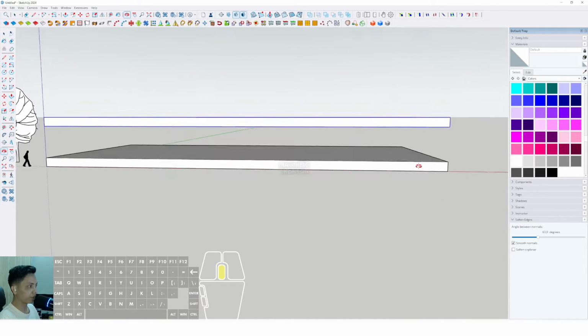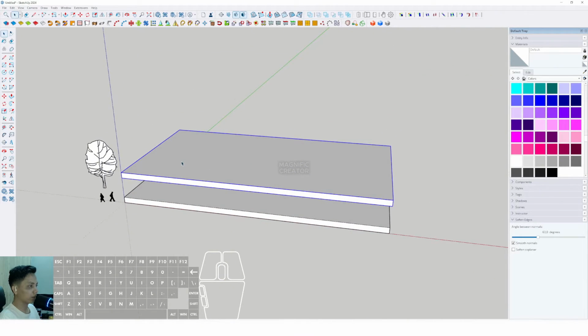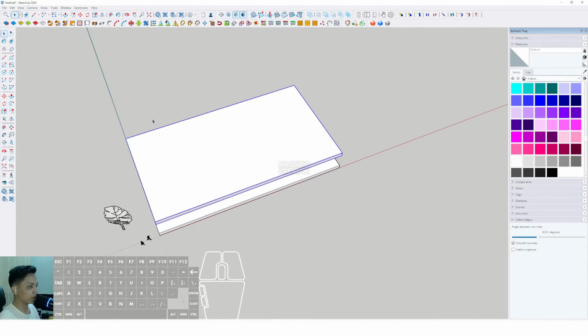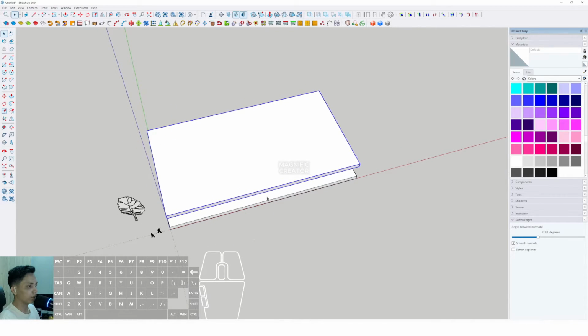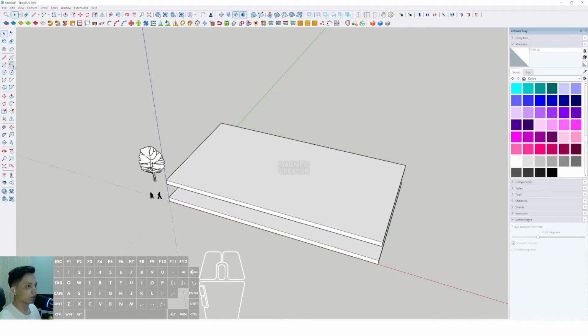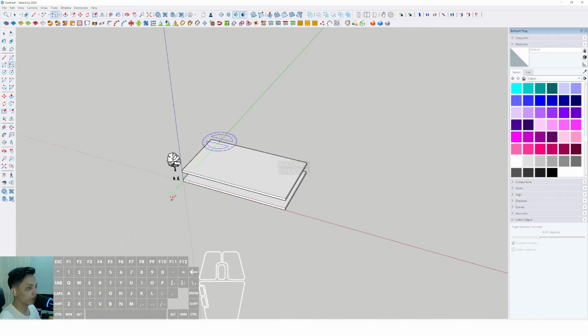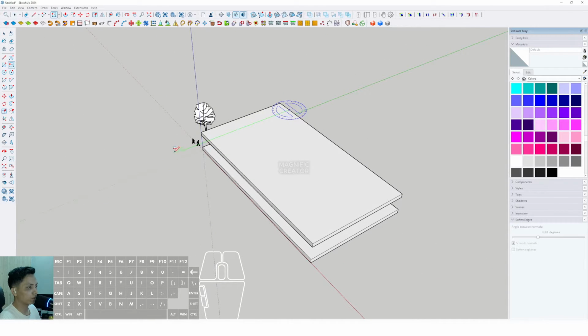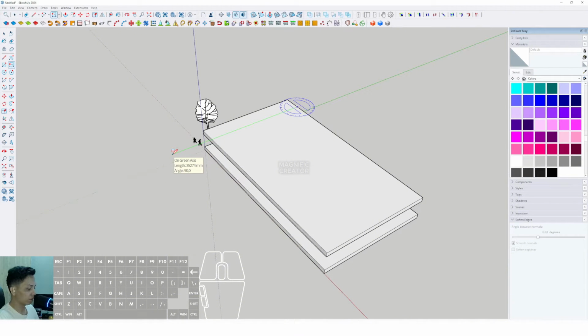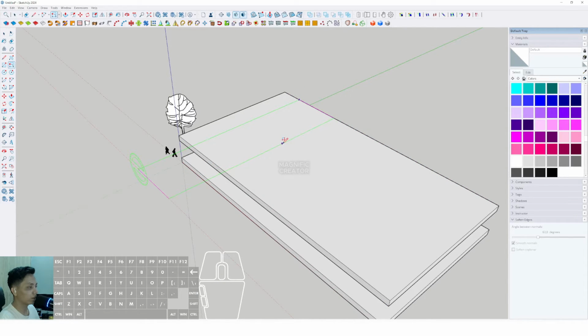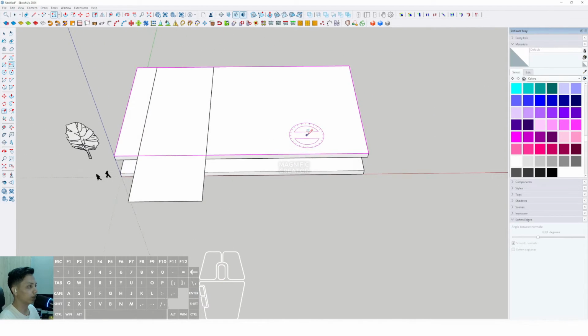Okay, then we can make another meshing here. We can make the inclination, we can make the intersection meshing in here, also using the rectangle. We can use the rotate rectangle, and then we can click from this position and click over this meshing, over the ground meshing, around 35 meter and enter. Then we can set the height of this first trapezoid meshing. We can drag to the other side around 12 meter and enter.